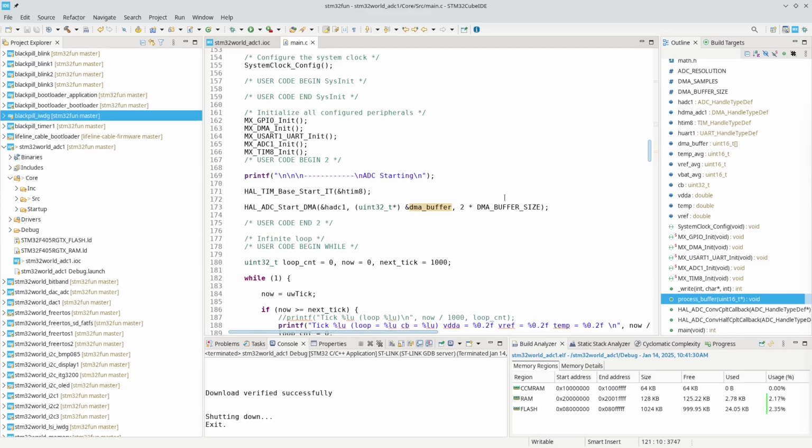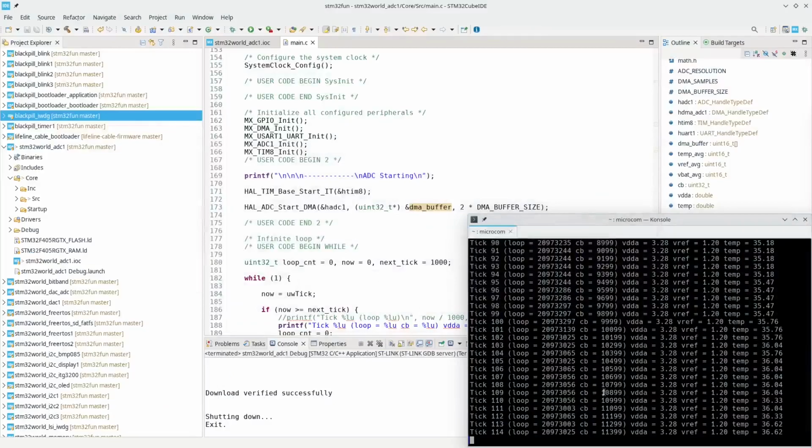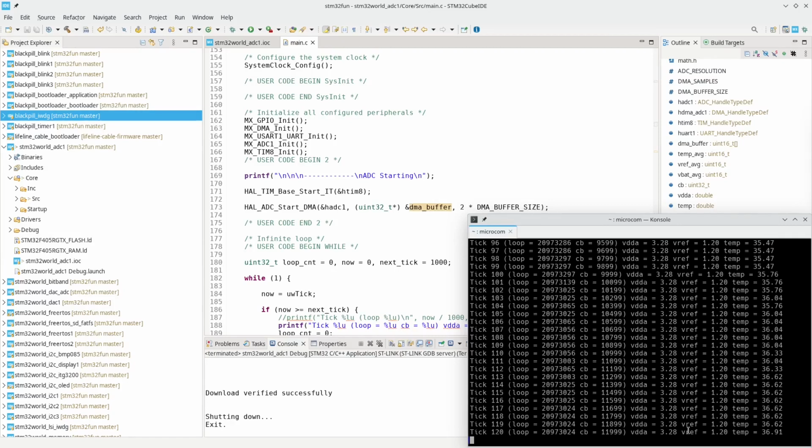In this case, we're not using FreeRTOS, but we are measuring 3 different values every time. And an interesting thing is, if we look down here, remember we started up, it doesn't affect the MCU performance at all, because all this is running in background.